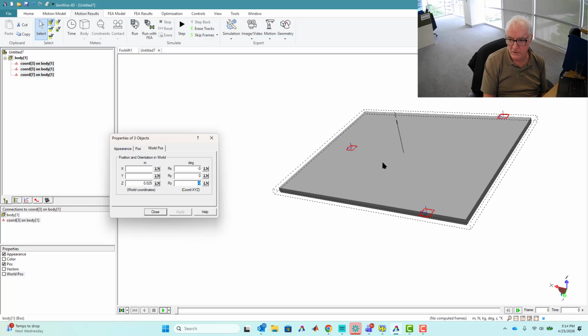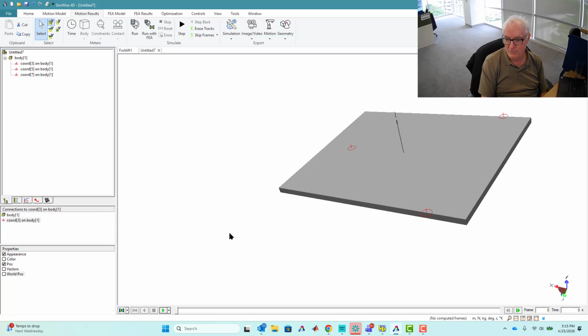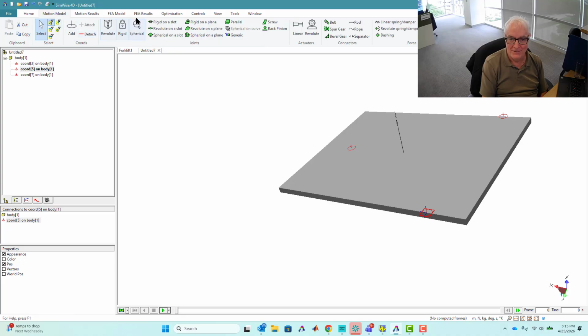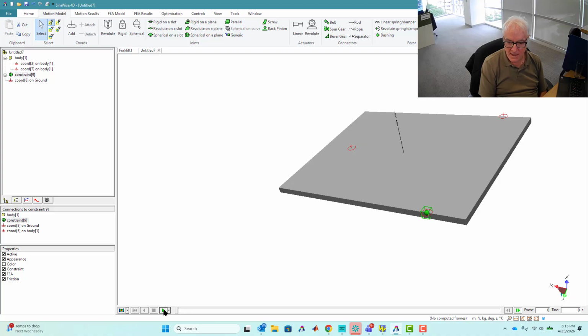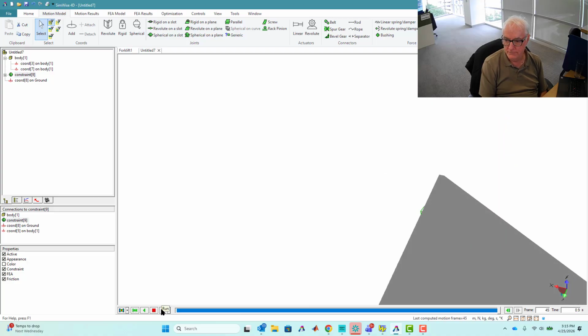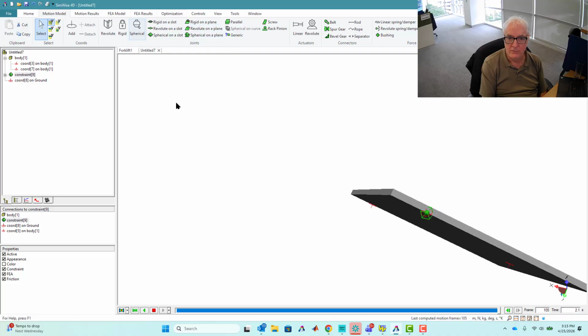Because as we move into Simulink, these orientations will be used there, and we're going to do all kinds of measurements through these coordinate frames. So again, there's convenience in matching the world orientation. Of course, in Simulink, you can always do the math yourself, but math is hard sometimes. Okay, so with those all set now, I think I am ready. Let's put it in the spherical joint. Great. And with that, we would get this kind of motion. It just flops all over the place.